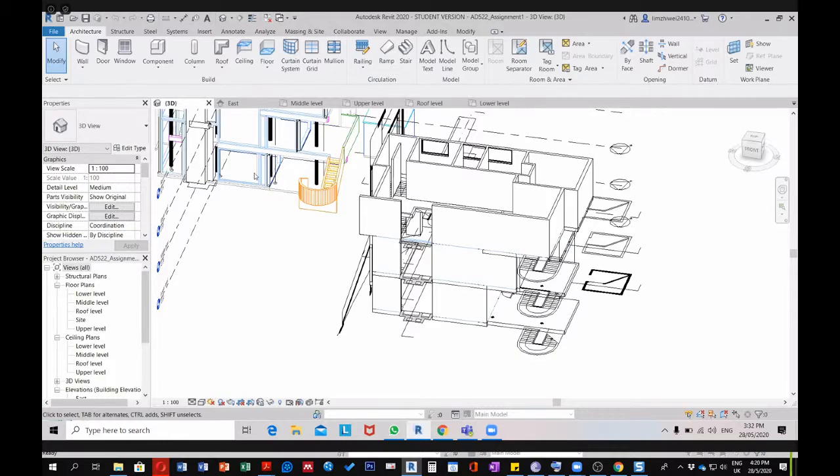So as you can see, it's a very similar process. For the wall, in order to change the thickness, you go to edit type, then you duplicate, rename, and then you change the parameters. Same thing for windows also. You duplicate, you change the name. Of course, you did already the measurement, and then you enter the new parameters here.